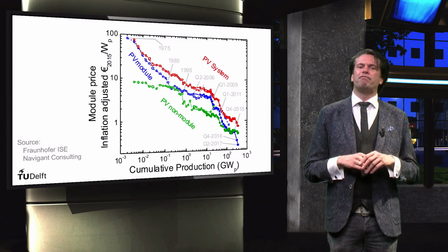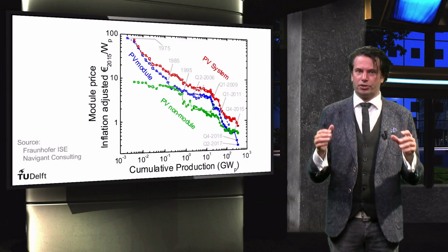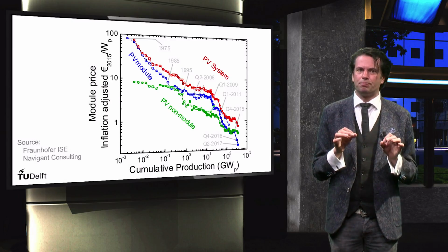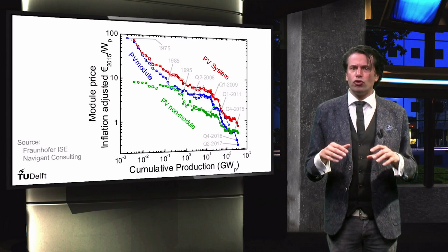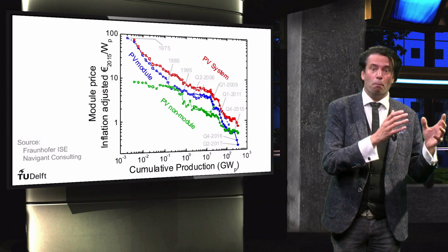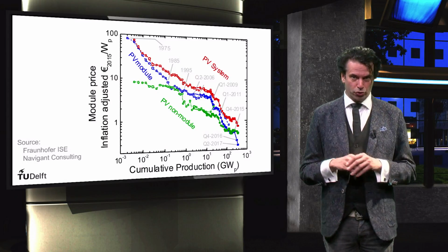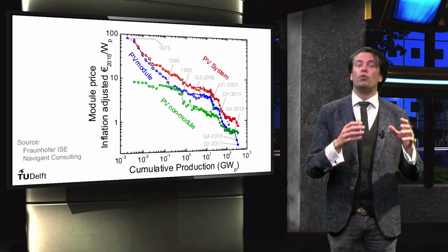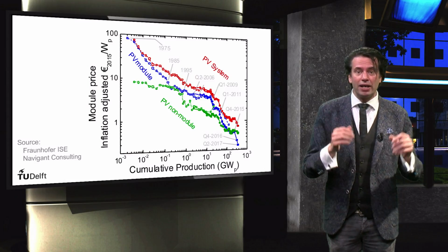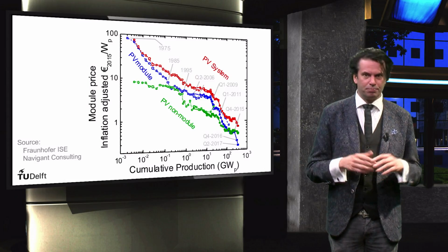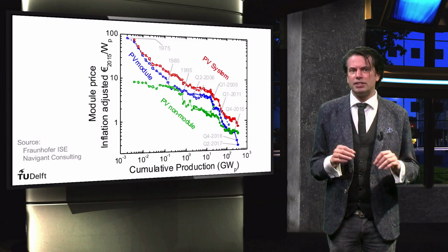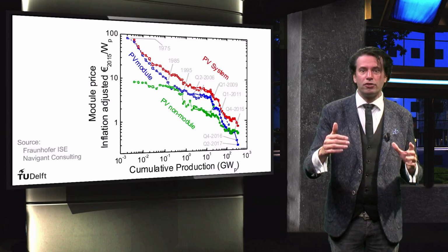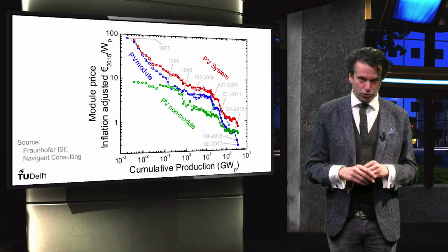This is the reason why the efficiency of modules is important if we look solely at the metric of cost price of the solar electricity. Since the cost of the total PV system consists of the module cost and the non-module cost. The non-module cost, often referred to as balance of systems, includes the racking, the inverter, cabling, maintenance, battery, etc. For simplicity, we assume that the non-module costs are the same per square meter for all types of PV modules.